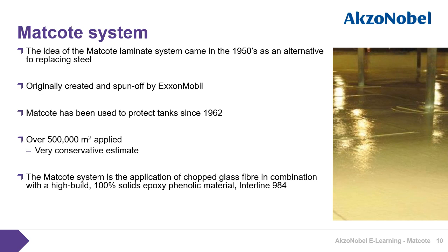The Matcote system itself is the application of chopped glass fibre in combination with a high build 100% solids epoxy phenolic material, typically Interline 984.